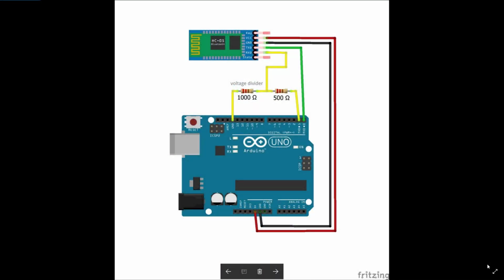You can use the HC-05 with pretty much any microcontroller with UART capability. I'm using it with an Arduino Uno, but the two devices operate at different TTL signal levels. The Arduino runs on 5 volts, whereas the HC-05 runs on 3.3 volts.